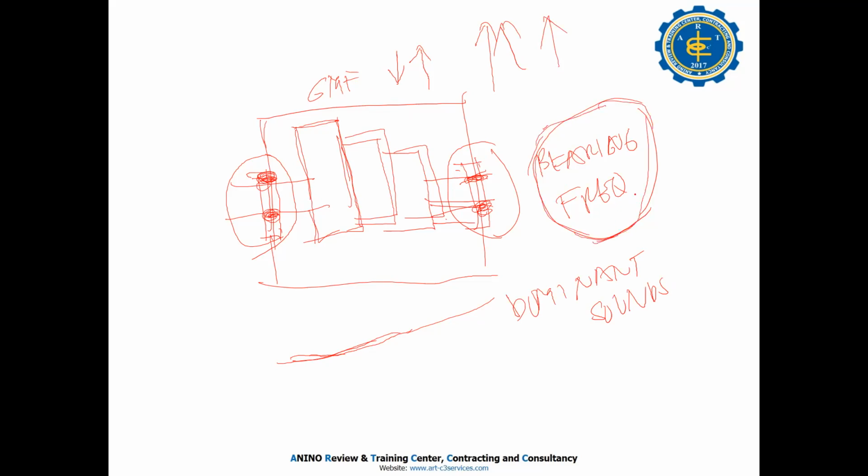So the gear mesh frequency shows a problem, impacting, there are spikes here. Spikes, right? It looks like a gear problem, but that's not your bearing problem, bearing damage. As per experience, we have many gearboxes in the plant. We open the gearbox, then we inspect the gear. There's no problem with the gear. We change the bearing.